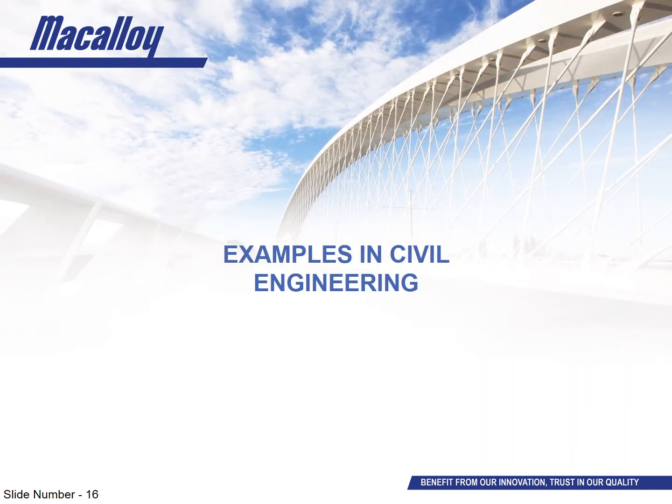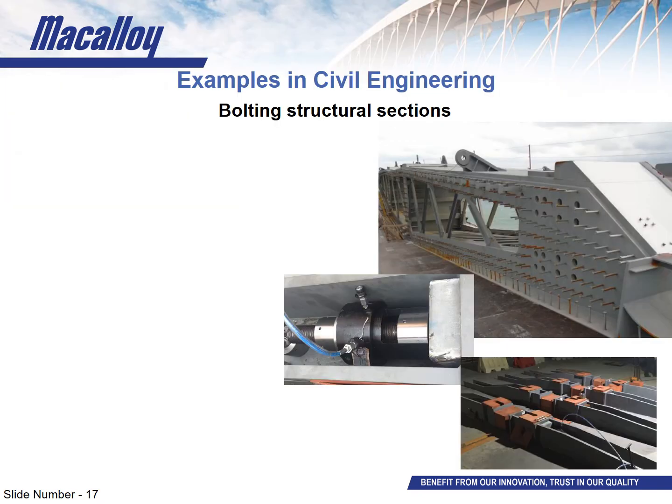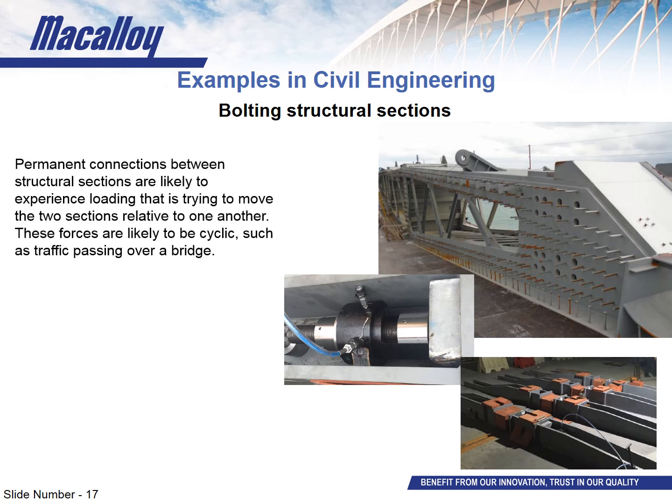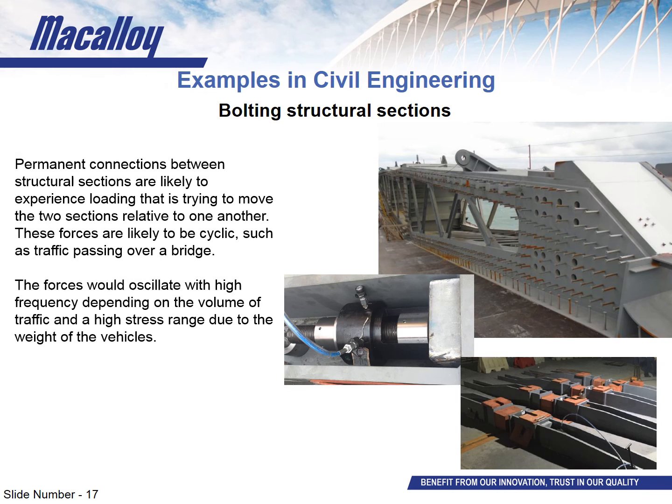Now we've talked over the various factors, I'll talk a little bit more in detail about the various examples that I touched on earlier. The first application is bolting together structural sections, and the best example I can think of is connecting two decks along the span of a bridge. As the traffic on a bridge passes over it on a day-to-day basis, the weight of those vehicles imparts a force that wants to move each bridge section relative to its neighbours. The high volumes of traffic quickly racks up the number of cycles, and the stress range can be high due to the vehicles such as cars, trucks, or even trains being very heavy. The forces would be a combination of shear, bending, and via prying some axial force if left alone, giving the potential for some huge stress ranges.